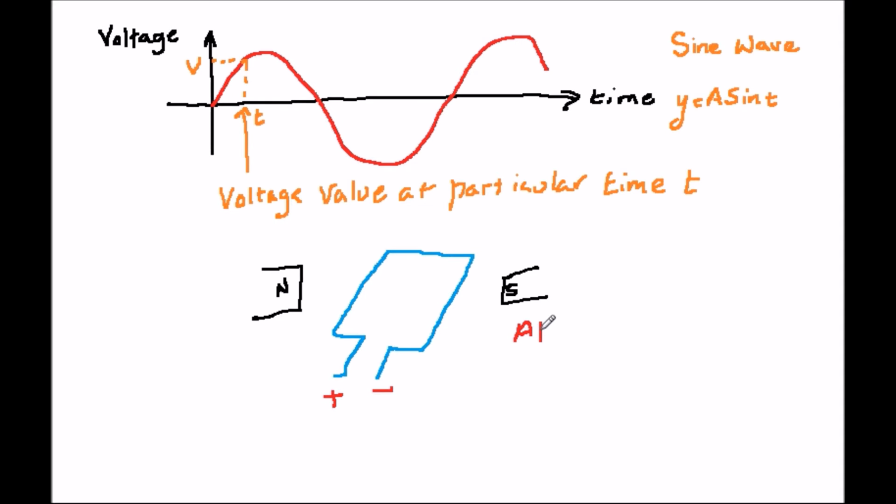This time we apply the voltage to the coil, and as we learned previously, this makes it into a magnet. Because of the interaction of its magnetic field and the magnetic field of the magnet, it starts turning. When it's halfway round, we need some, typically mechanical contrivance, to flip the plus and the minus terminals around. This will ensure that the force is always in the same direction.